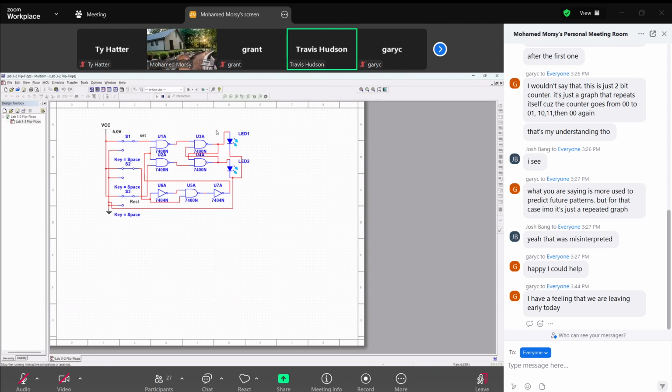Professor, in the lab packet, under the second portion, the positive edge triggered SR flip-flop, it has indicators. It doesn't have LEDs connected to ground. We have LEDs, but it's not necessary. You can use probes also here. You can get LEDs also. But it's not necessary to put LEDs. You can use the same as the one we used before, the sub-probe, either red or whatever.